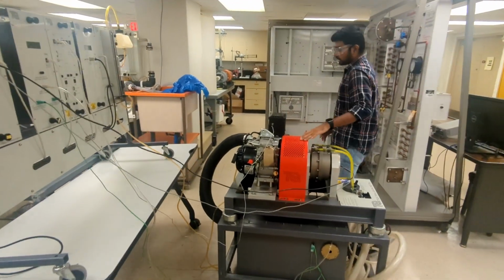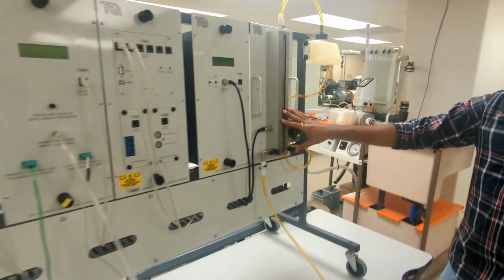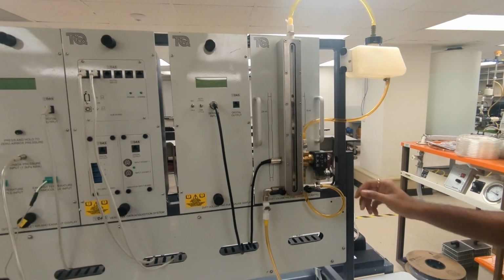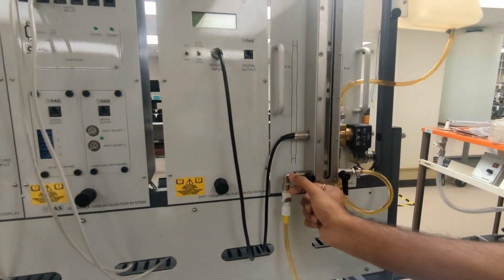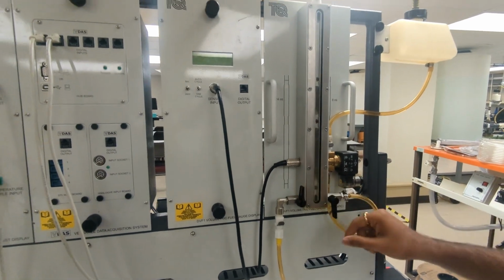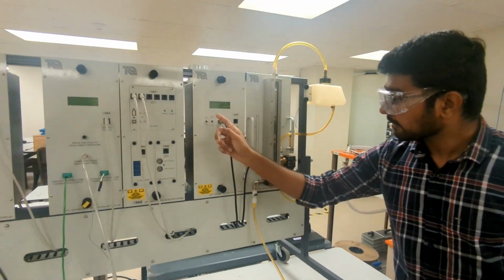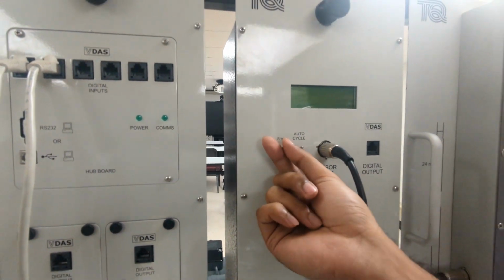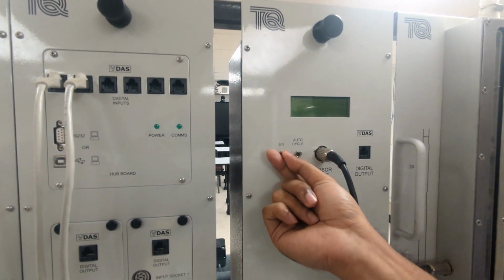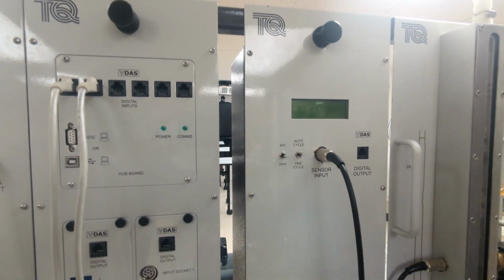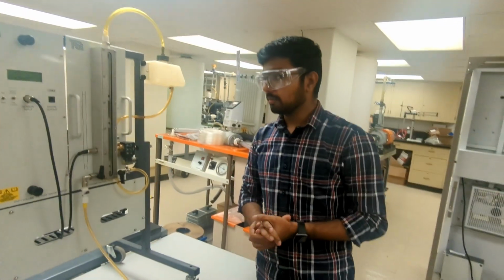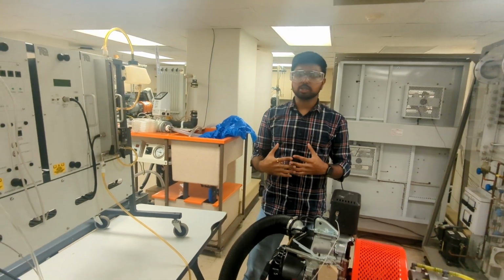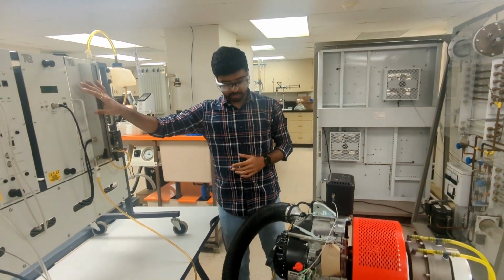Okay, so I will come up over here. Firstly, we need to make sure we allow the fuel to come into the input channel over here. Please make sure this is open, this is also open over here, and here you should select auto cycle like this. There are also two more options, like whether you need 8 ml or 24 ml. It's up to you. Usually you can select 8 ml, or you can also select 24 ml. That doesn't matter much. But on this screen, you will have the input of how much fuel is consumed. That means you will get the fuel flow rate from the screen over here.